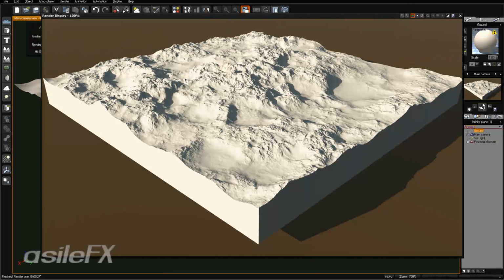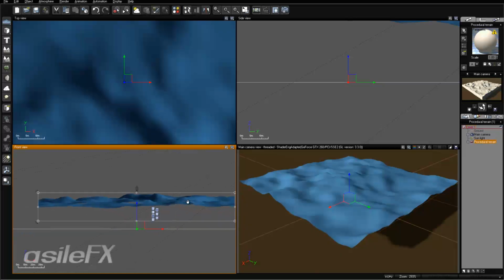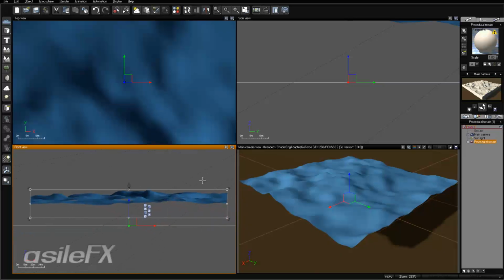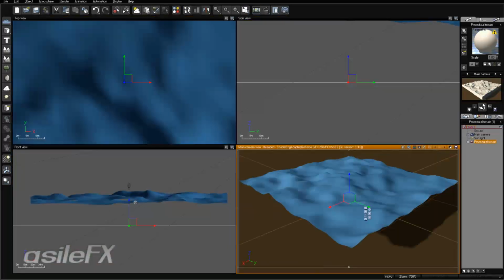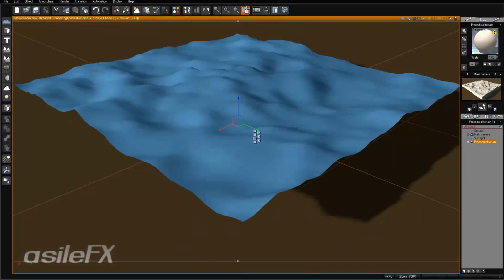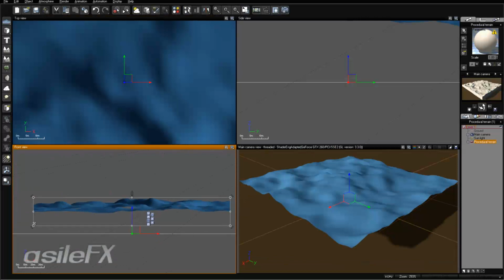Okay, so we can see the outer area of the terrain was being cut out, and then the main portion of the terrain. And it is a little bit above the ground plane. In order to see exactly to what extent it is going, if we switch over to the four viewport mode, which you can do by double-clicking on the top of the viewport, that'll switch it over. You can also use the buttons up at the top to toggle between the different viewport modes, and then click in a viewport in order to make it active. The box that we see around the terrain is going to be the full elevation or the altitude of the terrain, and that's important for controlling the altitude and the way we're going to control it with a parametric mode.